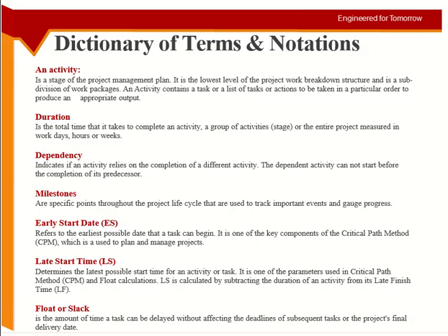So, duration is the time taken for one activity or a group of activities which can mark the end of a stage, and it can be in terms of days, weeks, or hours, depending upon the type of activity you have. If it is just formwork, it can be in hours. If it is concreting, it can be in days. If it is design, it can be in weeks.